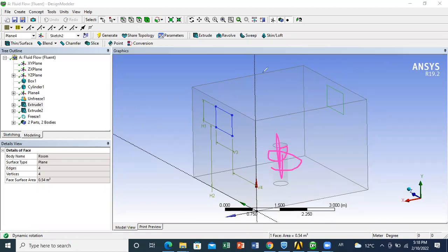You just care about the exchange between the lateral surface of your cylinder and the environment, because this will affect temperature distribution in the space, because you know that the person will release heat flux and then will affect the temperature around the occupant. So since we don't care about what is happening inside the body, we can remove it.